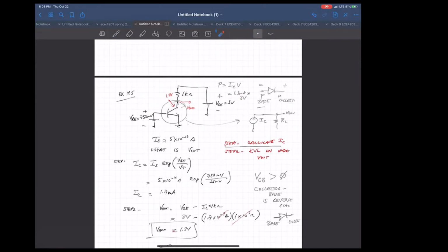There'll be a huge push to reduce this voltage, and that's why I'm saying this design is pretty conservative. If you want to stay conservative, you can do it like that, or you can maybe come down to a VC of, I don't know, 2 volts. But you won't have a lot of operating margin, because in practice, when you're building products, you can't always guarantee that a 3 volt power supply is going to be exactly 3 volts.